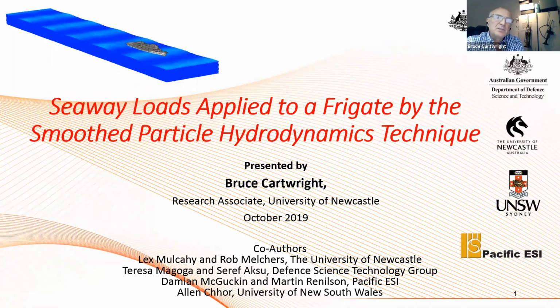But there's an interesting kind of catch-22 here, and that is that you don't want to go and redefine the RAO for every boat that you're going to analyse. So what we're hoping is that once we've done a good validation for one particular boat or ship, and under those conditions, as long as we don't change our parameters in our model too much, I would have an extreme amount of confidence that if we change the hull shape, the predicted response is going to be very accurate.